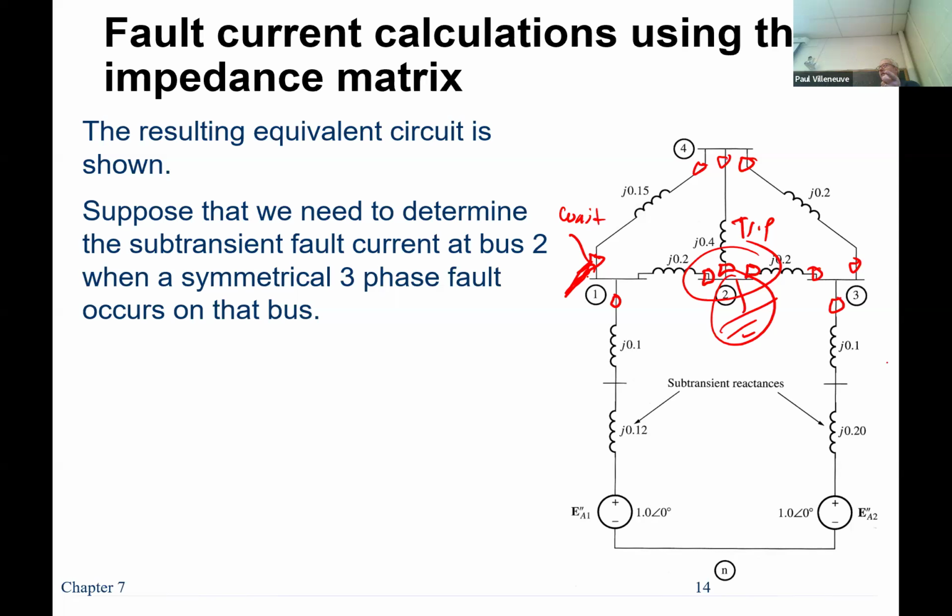You just made the job so much harder because now you've isolated a part of the system that has no failure whatsoever, but I definitely have to verify that that section of line is all healthy and good. And it's one of the scariest things. I can tell you when I was fairly new in my career, I had designed the electrical system for a power plant, and they had energized a 150 MVA transformer, and it tripped just like that upon energization.